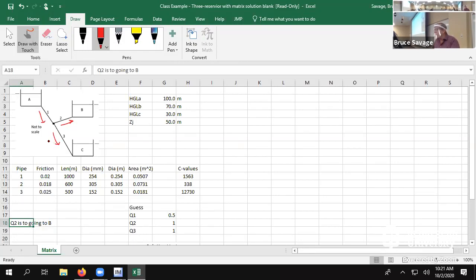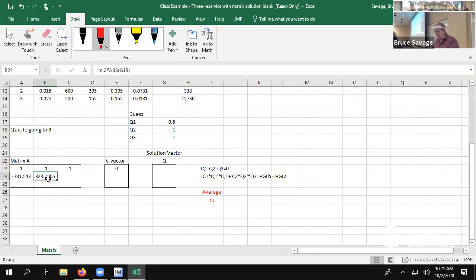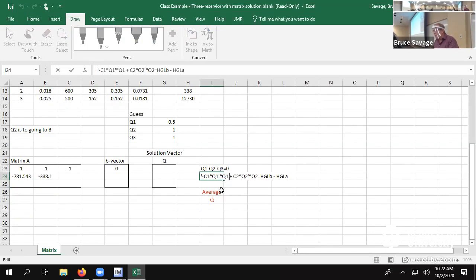Oh, I did that wrong, didn't I? Thank you. Because I'm going 2B, so I'm going with the flow, so it should be negative. So you're absolutely correct. So this should be a negative value. Thank you. Because if I'm going with the flow, I'm going down the hydraulic grade line. So over here on my equation, that should be a negative value. Okay, make a little more sense? Okay, thanks for catching that.